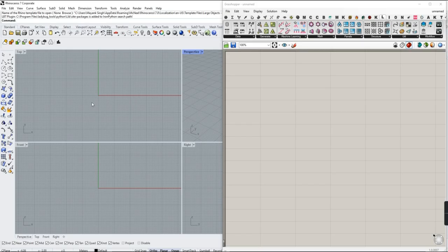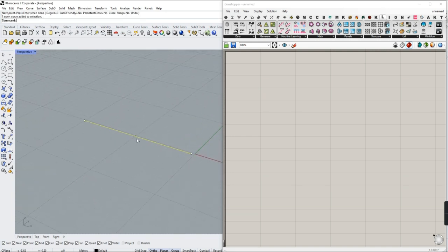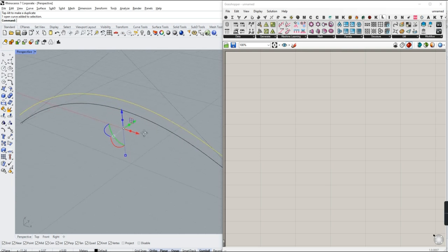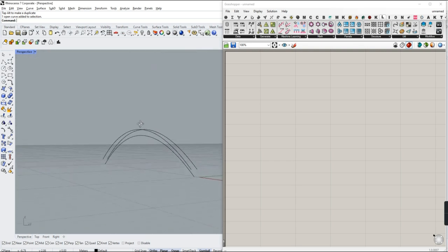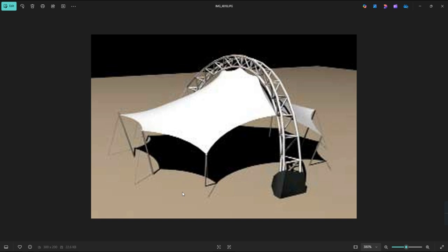First, I'll draw three curves. The easiest way to make a curve is using the curve command. I'm using, let's say, somewhere around like a 20-meter span. I'll switch on my gumball and I'll pull this point up, and then I'll again use gumball, maybe let's say 600. I'm using meters, so 0.6, and then take it using gumball again, maybe 0.3 and minus 0.6. So basically I'm just using gumball to create this sort of triangle. And to get this truss, basically I've just got these three curves.